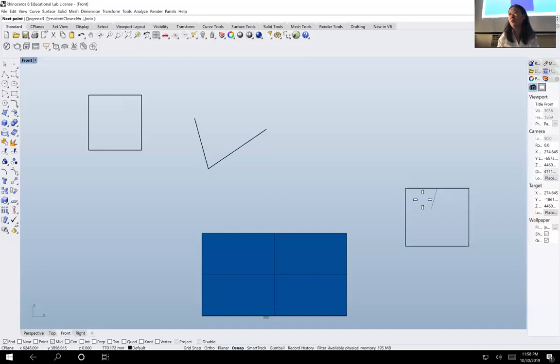So this is the middle. I started from the middle. I'm going to draw a curve because it's a curve, yeah. As I go along, I would also use another one called the near, N-E-A-R, so that I would be on this line, because if I don't use near, I could be inside or outside the box. If I click on near, I'm really perfectly on the line, near the line. So if you want to get the point that's really near the line, you can do it.